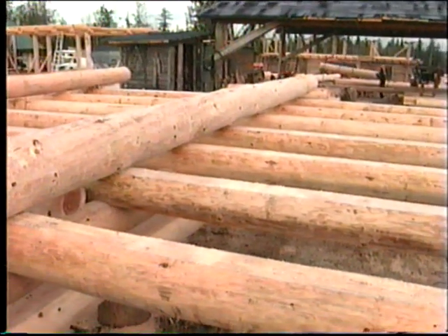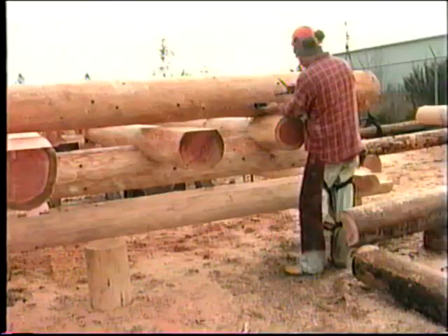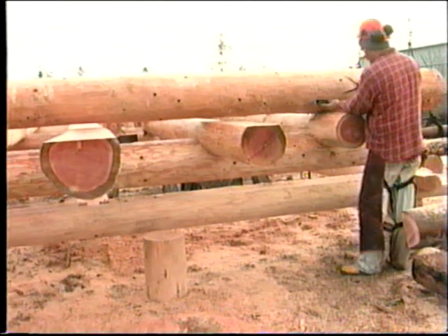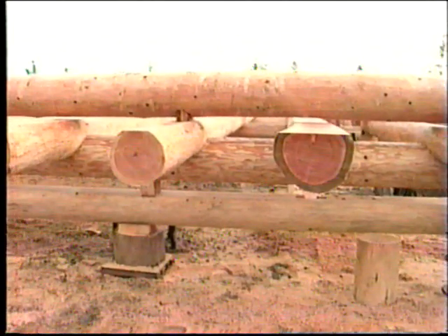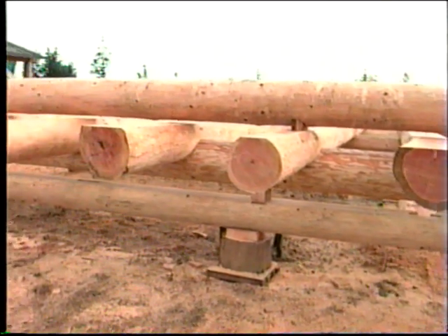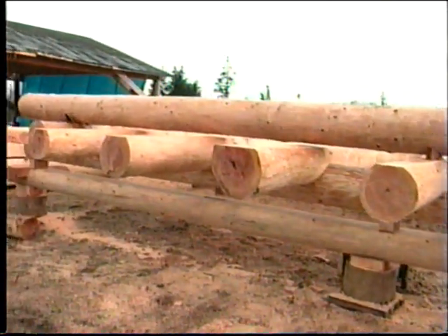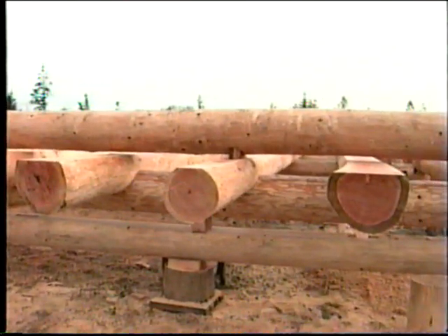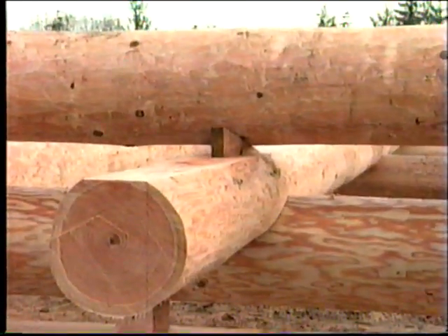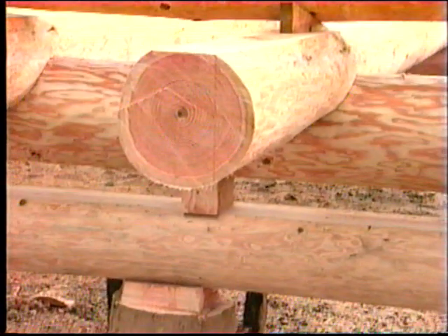If you have removed the top logs of the wall to the ground in order to fit and level the floor joist, take this opportunity to set, scribe, and cut the flat on the top of the cap logs. If your building is large and the cap log long and heavy, it may be a good idea to block the setup at the center to keep everything in line.